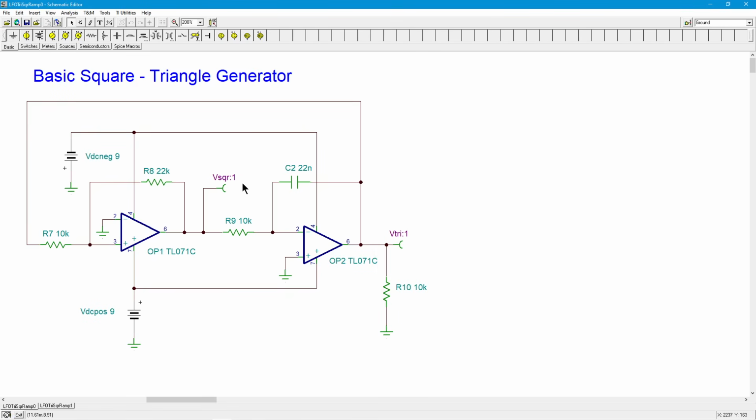There's no convenient way in this circuit to create a sawtooth. To create a sawtooth, we would actually need to change the charge and discharge times, in other words, the currents that are feeding the capacitor, between the positive and negative cycles. Right? In other words, on the charge up versus the discharge down, or charge down, however you want to call it, because either way it's active, right? You would have to be able to change those to get some kind of sawtooth out of here. Well, you can do that.